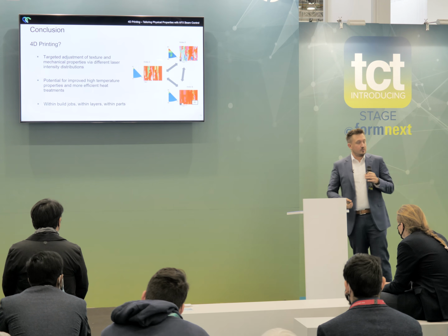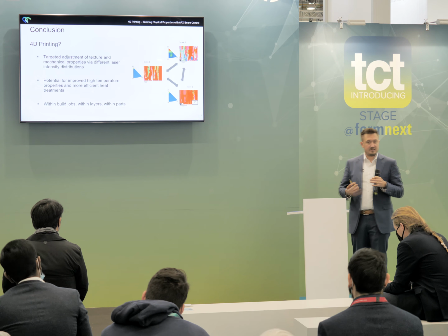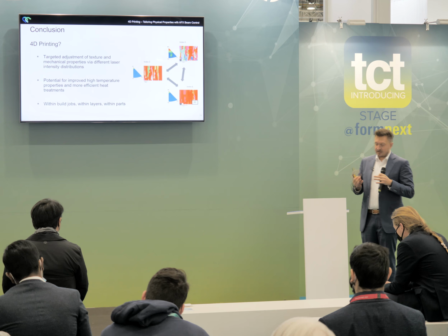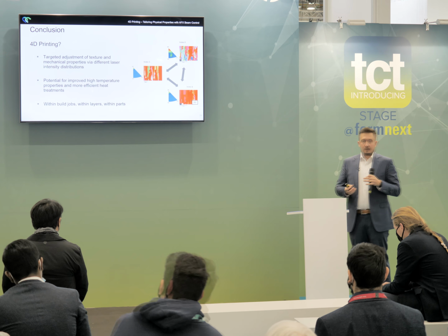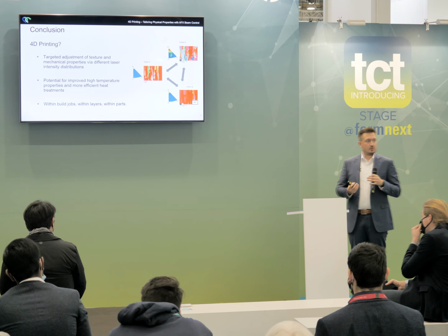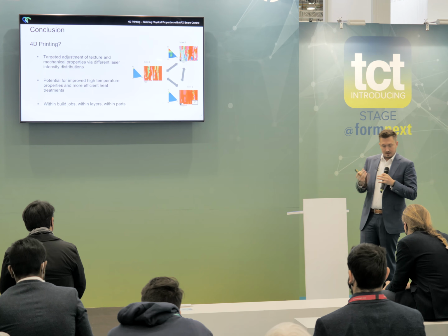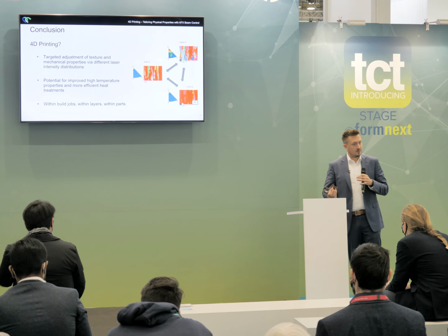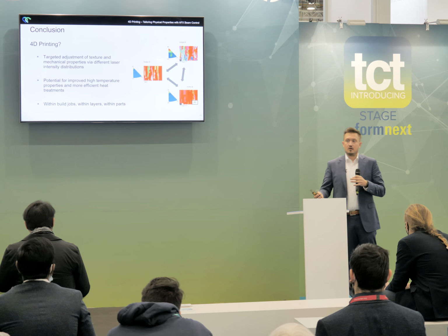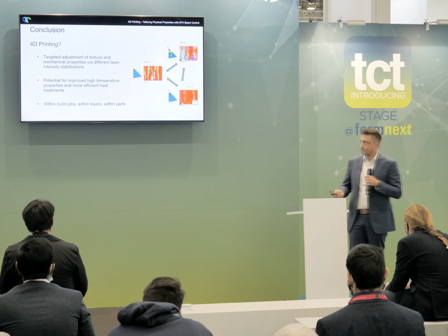So to draw an interim conclusion, by 4D printing, we mean that we deliberately manipulate the solidification conditions in order to tune the mechanical properties towards our application. And of course, this also opens up new possibilities in terms of high temperature properties like creep resistance, for example. And since it's a parameter like any other parameter currently, we can do so not only from job to job, but even within a single layer, or use several different processing strategies within a single part.